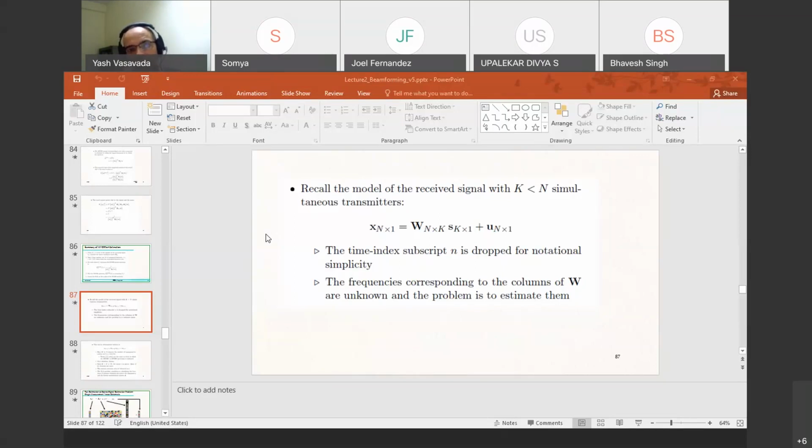If you try to suppress the side lobes, you have to give up on the width of the main lobe. All of these other windows allow you to suppress the side lobe, but their main lobe becomes wider than the rectangular function. So that is a trade-off that is involved in the design of the power spectrum density-based spectrum sensing techniques.